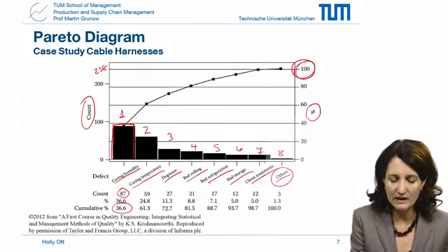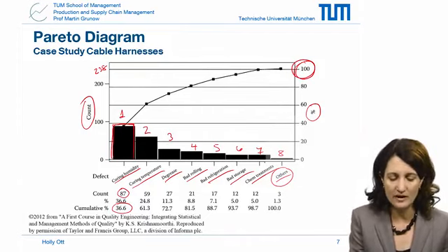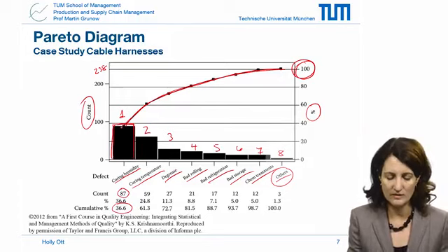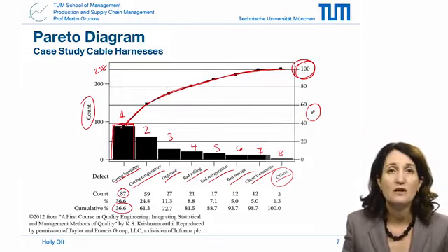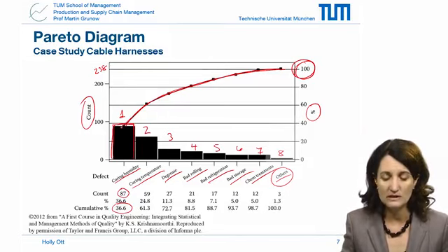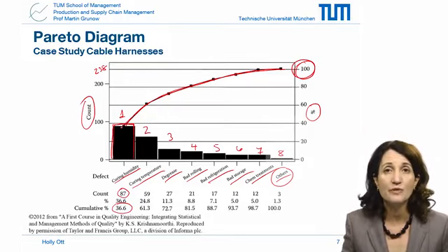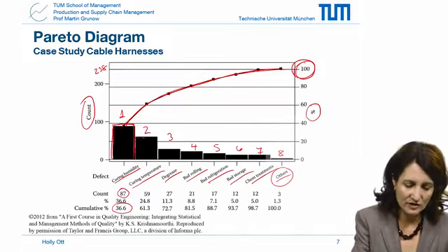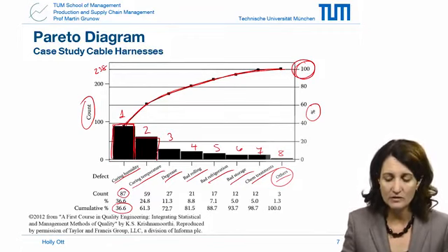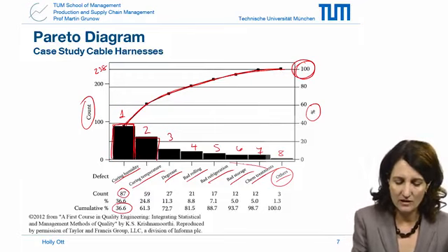So these are ranked, and you can see in a very clear diagram the count and the percentage frequency, which is plotted here in the Pareto diagram. This graph and the table help you to see the most important causes. So here we've got curing humidity and curing temperature, clearly showing a higher impact than everything else.